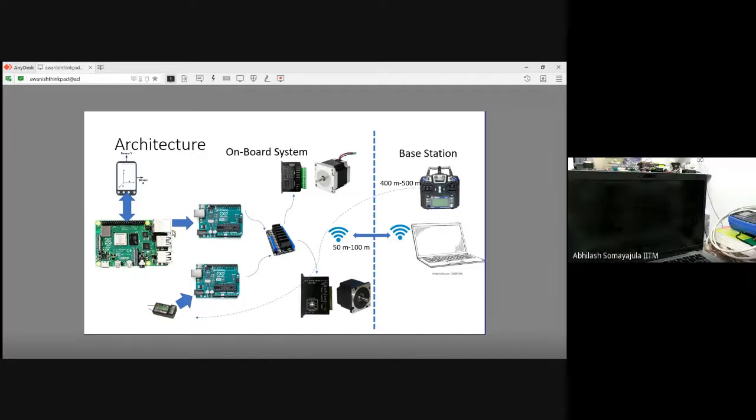So I want to cut the Raspberry Pi and completely switch to the RF manual control, which we can access through a joystick. You can think of this as follows: let's say you are running a turning circle experiment, holding the rudder at a certain position and executing a turn. And you observe that there is a tree in between into which the ship is going to run. So you want to stop the experiment and take over control of the boat, isn't it?